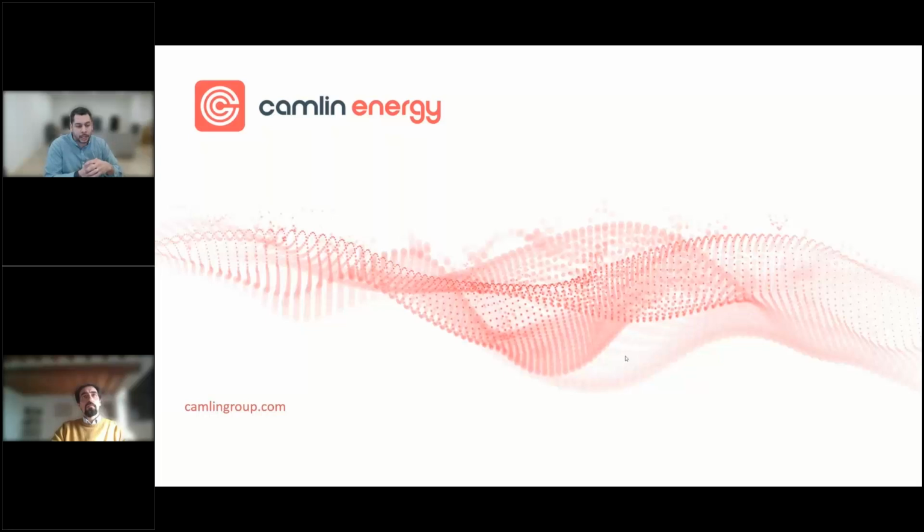But for generators pre-equipped with 80 picofarad sensors, terminated externally to the generator, this is fine, and many monitoring systems can interface with those pre-existing sensors, so as not to create a major maintenance activity to have to install new sensors at 1 nanofarad. But that would generally be my guidance on that.